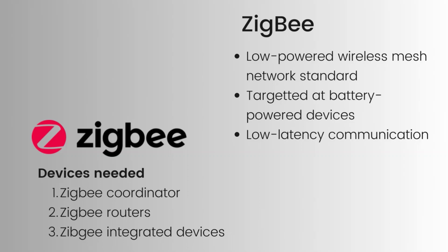For example, the health measurements of people such as heart rate and blood pressure, but this is not suitable for streaming data. Zigbee networks cannot exist in isolation and need to connect with other protocols to receive instructions and to store and share data with computer systems. Therefore, when setting up a Zigbee network, we require a Zigbee coordinator that acts as a gateway between Zigbee and other protocols such as Wi-Fi or Ethernet.